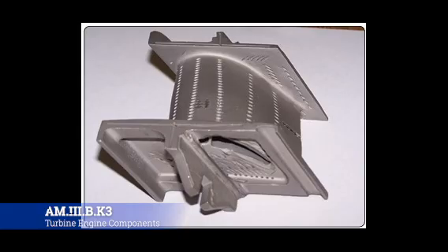So you're flying along thinking that everything's fine. All of a sudden, these things finally just give way because you hot started the engine or ran it too hot for too long or something like that. But that's how precise some of these tolerances are. Those holes there are designed at the right place, at the right size for a very specific reason, to help maintain a certain temperature in those fan blades.